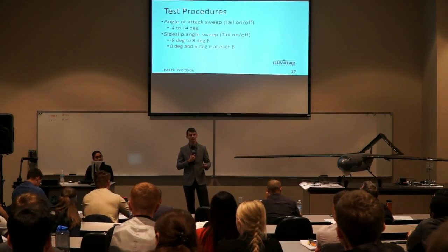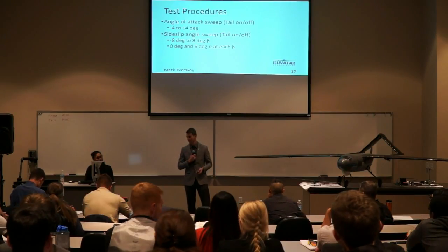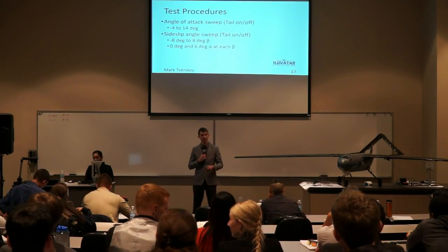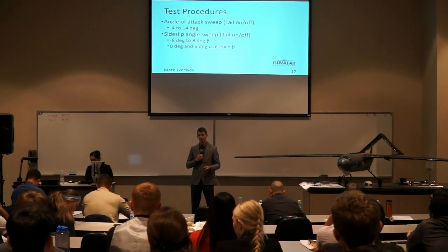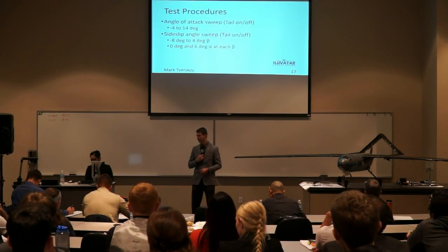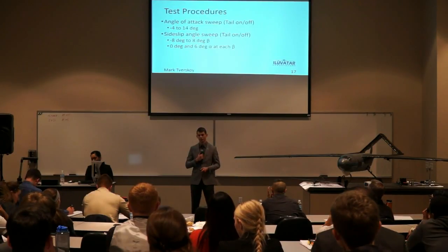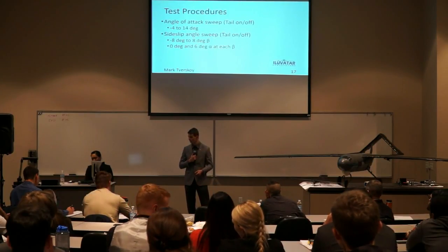We conducted an angle of attack sweep from -4 to 14 degrees with the tail on and off, and a sideslip angle sweep from -8 to 8 degrees with the tail on and off. The angle of attack was controlled with a stepper motor, but the sideslip angle had to be set manually by turning a screw under the tunnel. Each angle of sideslip was also tested at 0 and 6 degrees angle of attack to test for the stability derivatives.